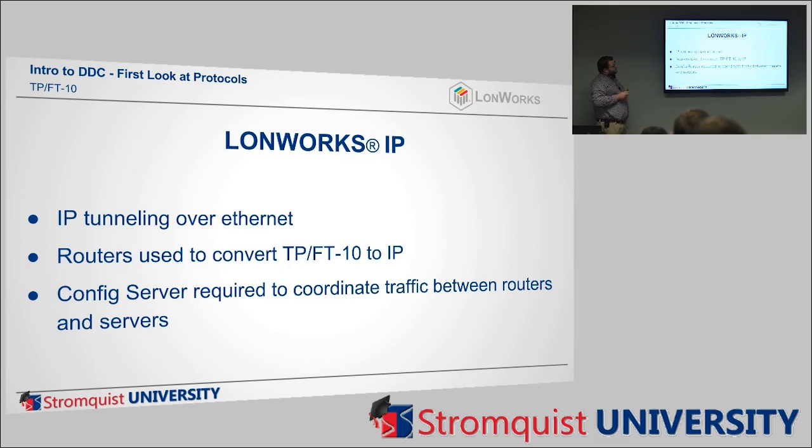And one thing, the difference between LON IP or LONWORKS and BACnet, and back up a little bit. There's always people saying, well, I like LON better, or I like BACnet better. To me, they both have advantages and disadvantages. The two main ones: LON is a lot more forgiving on the install. It's a lot more robust network. BACnet is a lot easier on the programming side or communication side. It's not as complicated as LON. LON can get pretty complicated when you're trying to get stuff to talk between each other.